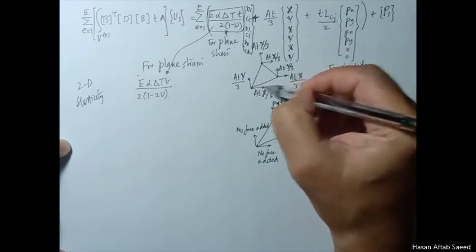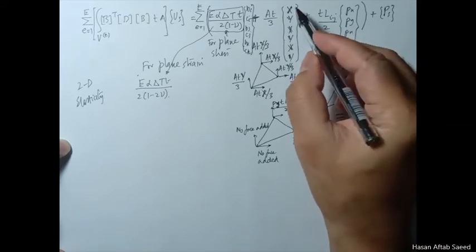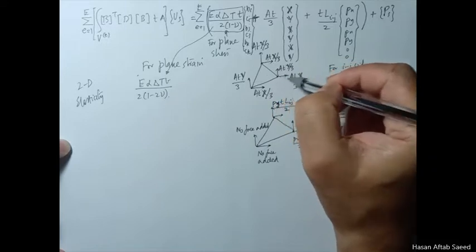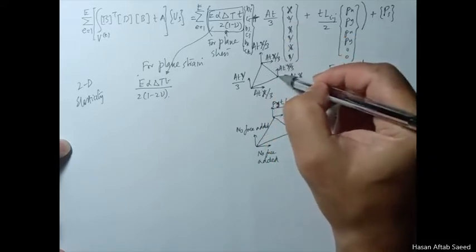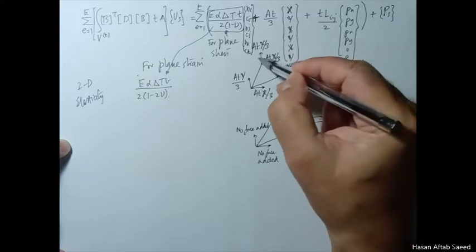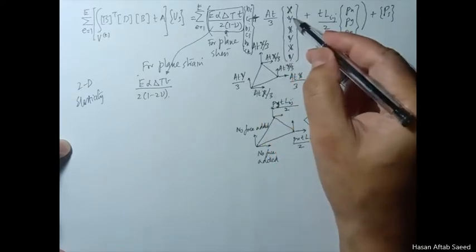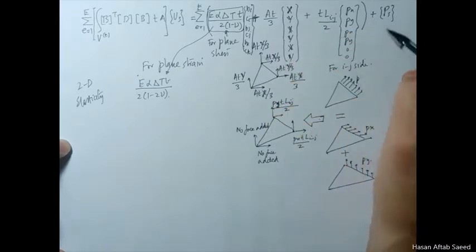Actually you are dividing the body force into three parts. The x-axis part is divided into three parts and then applied on the three nodes. Similarly, the y-axis part also gets divided into 3 and then applied to the respective nodes. If x or y happens to be 0 in some case, then that component will simply disappear.